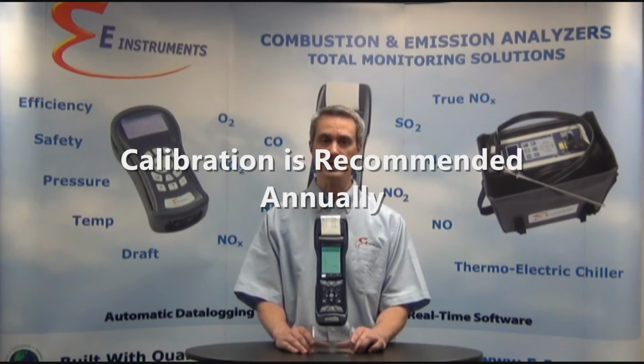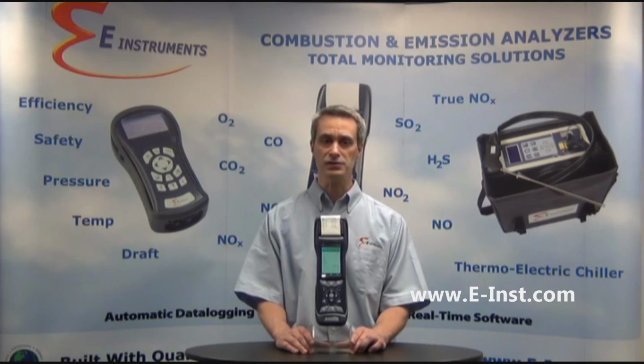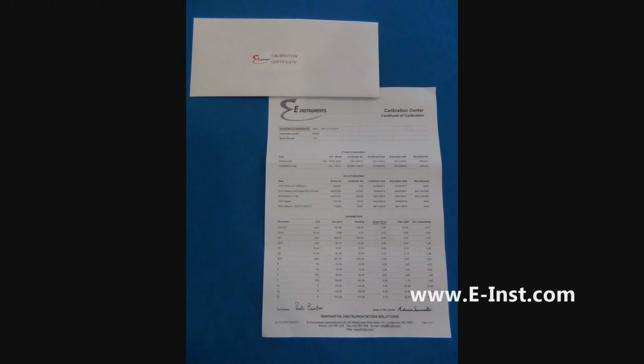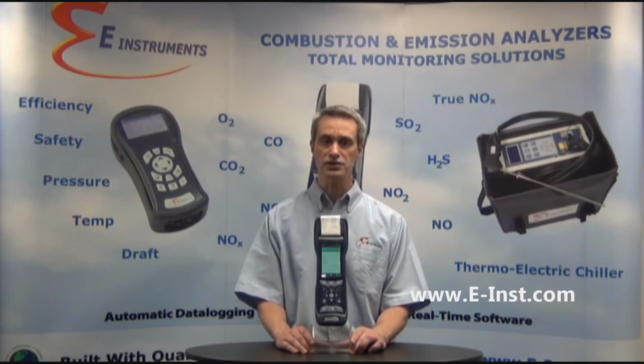Our factory recommendation for recalibration of the analyzer is at least once a year. You can send the analyzer back to E-Instruments for recalibration with a new calibration certificate, or you can calibrate yourself with proper calibration, span gas bottles, and calibration setup. The calibration procedure and details are included in the manual.